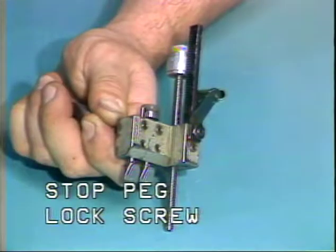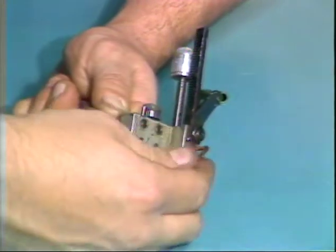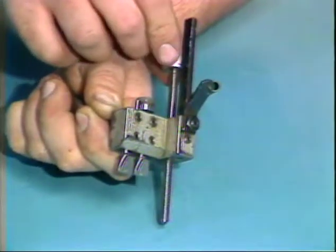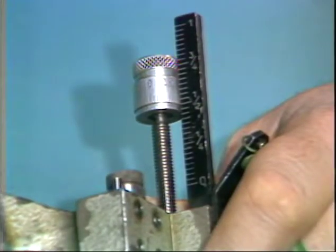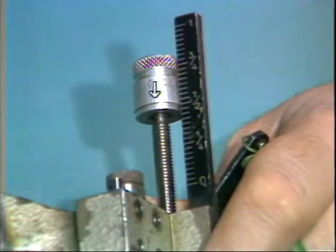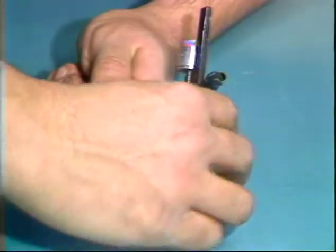This is the micrometer stop peg lock screw. Before adjusting the stop peg, the lock screw should be loosened. Before mounting the attachment, the approximate feed length should be set. The stop peg is turned until this edge on the micrometer approximately equals the desired feed length on the ruled scale. The lock screw can then be tightened.